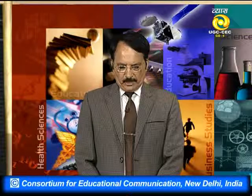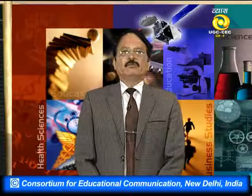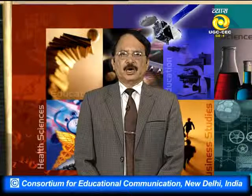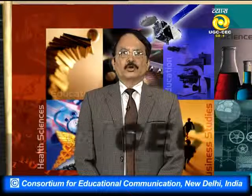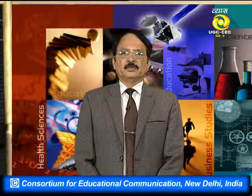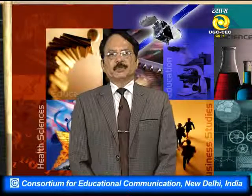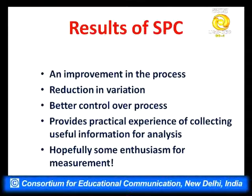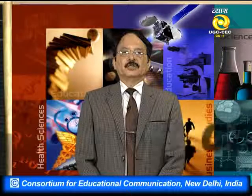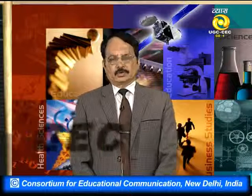And SPC also provides practical experience of collecting useful information for analysis. Useful information is like this: if 3 or 4 observations are going in one direction, maybe close to the upper control limit, this gives us information that something has gone wrong in the process, though these points are well within the control limits. Then we will have to see what has made all these 3-4 points go in one direction. Then hopefully some enthusiasm for measurement also. This gives some aggression to the person inspecting the process, that it is to be checked on a regular basis, and if anything goes wrong, it is to be detected very fast before it produces a lot of defective products.